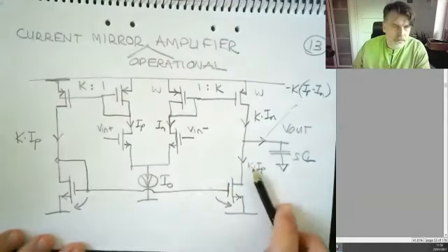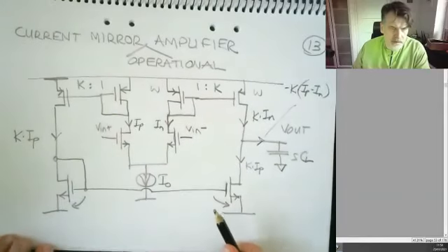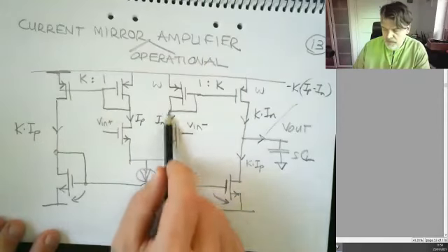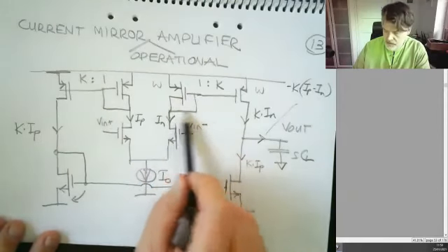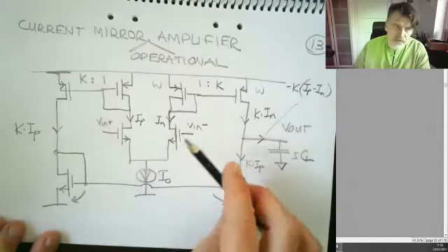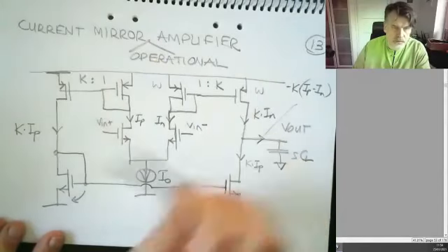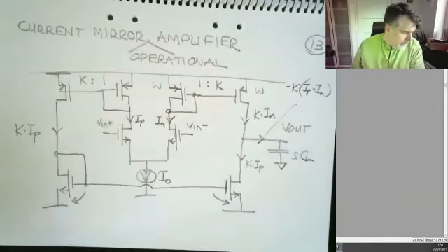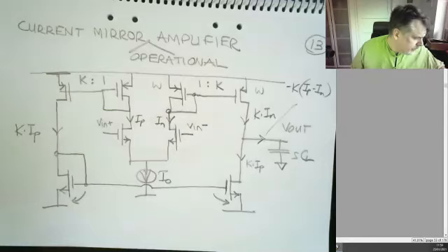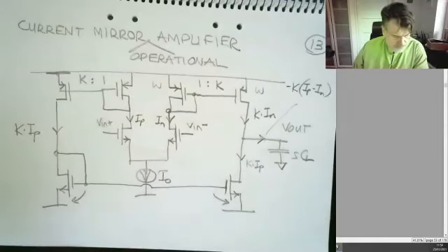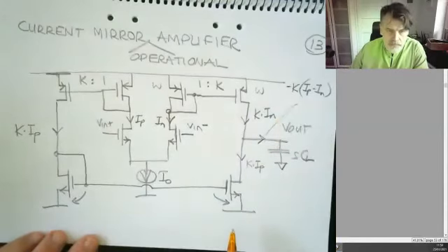Okay, so this is your first operational amplifier, the one you will work on in the lab, in the project. We have a common source stage here. We have some sort of load giving you some sort of gain. The current is mirrored and then terminated on the active load. So once again, one could argue it's a common source plus a common source. But the good thing is that the poles are separated. And if you want to find the poles, say from input to output, it's quite easy. You just follow the track from input to output in order to identify where they could be.